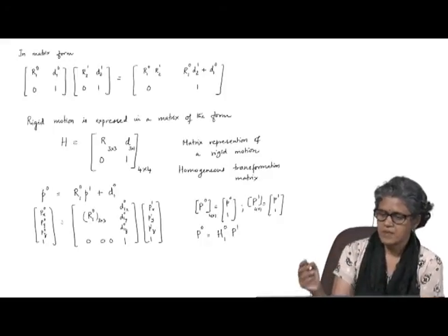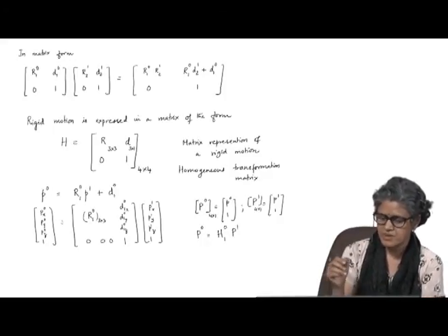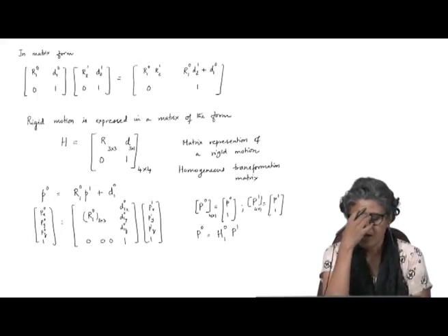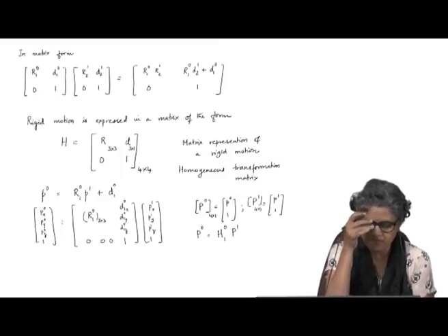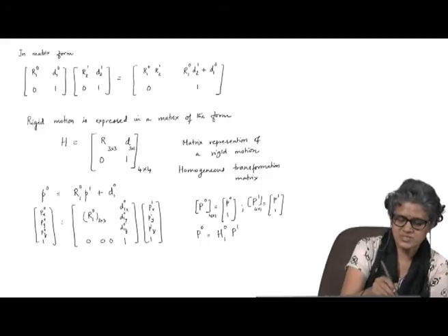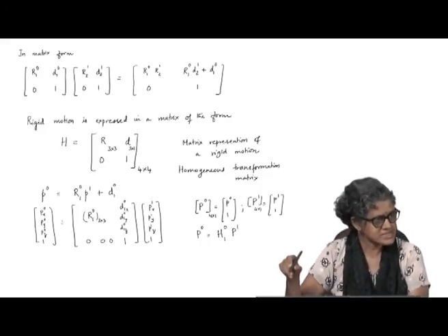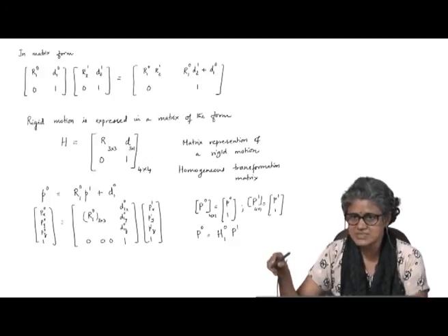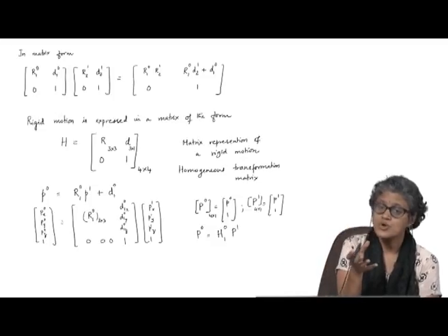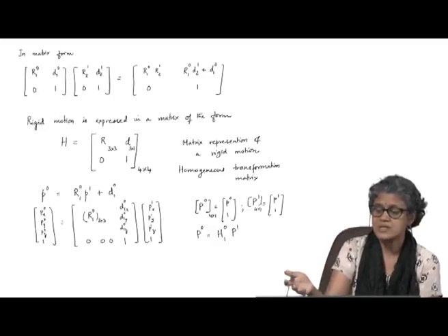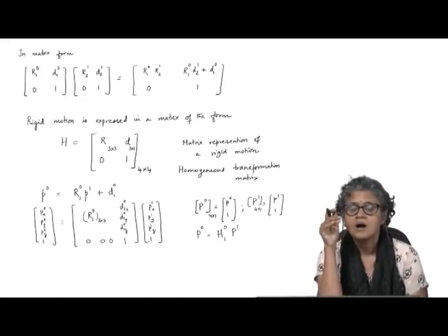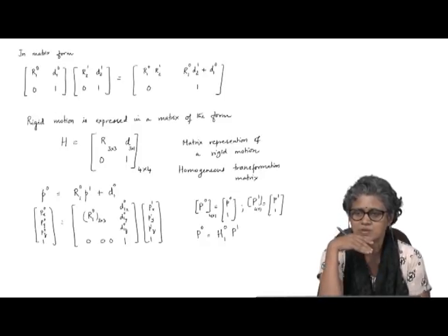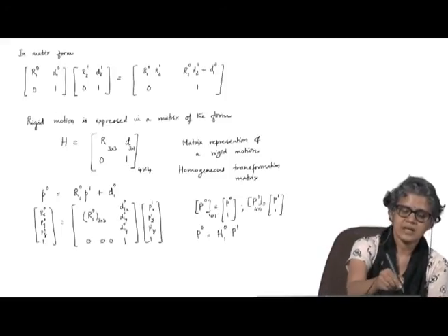So, you can use certain conventions to set up these matrices. Okay. The Denavit-Hartenberg convention is one, where you choose these coordinate systems. So, if you have n links in the mechanism, you choose the coordinate systems that you attach to each of these links, okay, and the coordinate systems rotate with the links, as opposed to the earlier case where we said we are choosing only the origin at the CG of the link, but the coordinate systems remain parallel to the ground coordinate system, or the fixed link's coordinate system.